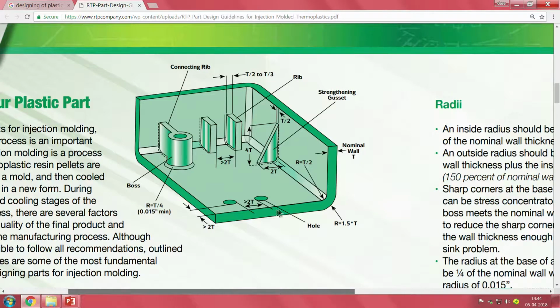And we come to actually issues in detailing. Most important is, this is where the difference between an injection molded part and a 3D printed part comes. In the case of these injection molded parts, we would have noticed that there is a rule applied everywhere saying the corners have to be made with a radius. Why is it? Because there is a nominal wall thickness, somewhere the material is injected and slowly it is supposed to flow along these lines, and when it flows along the lines,